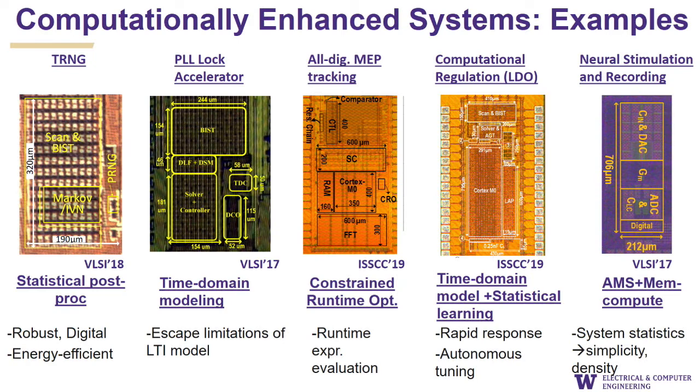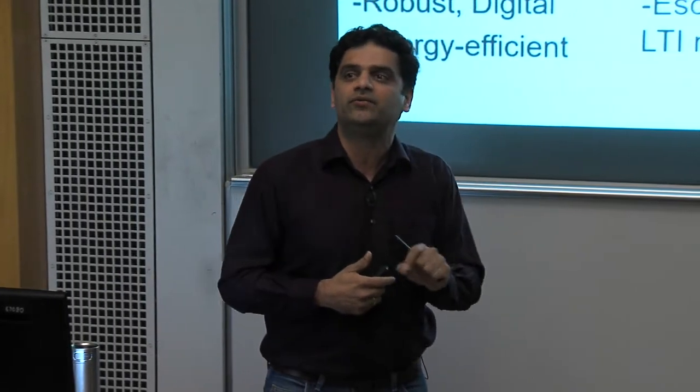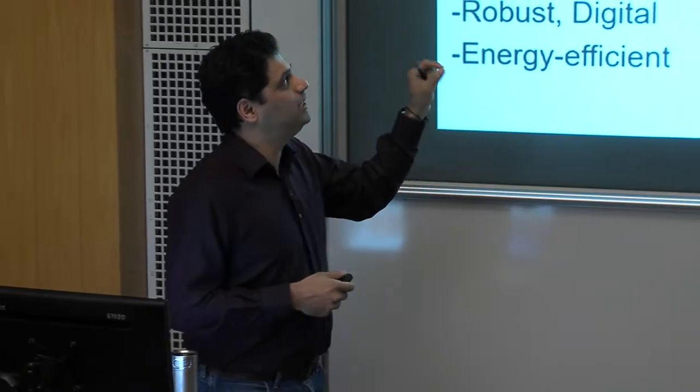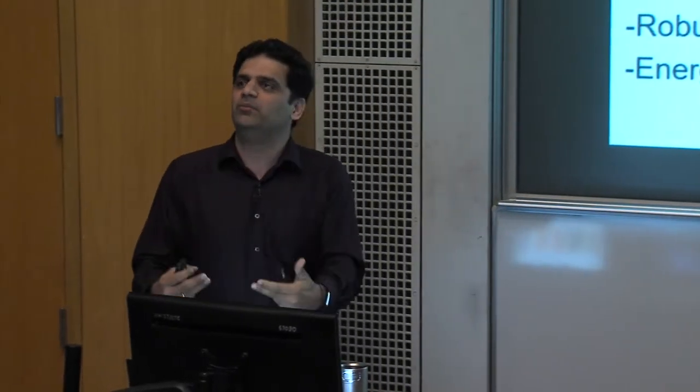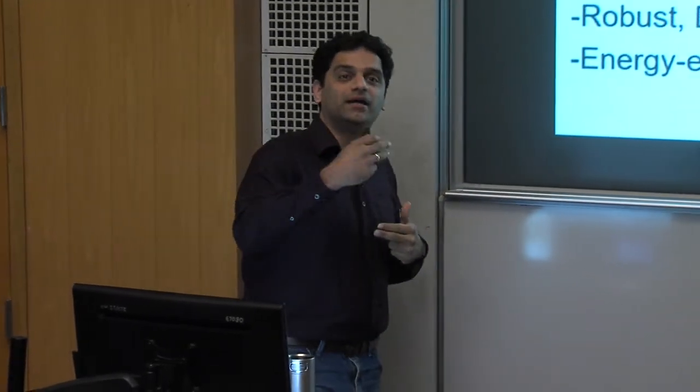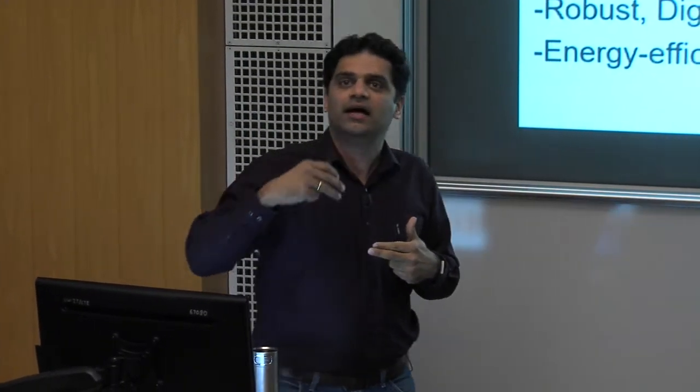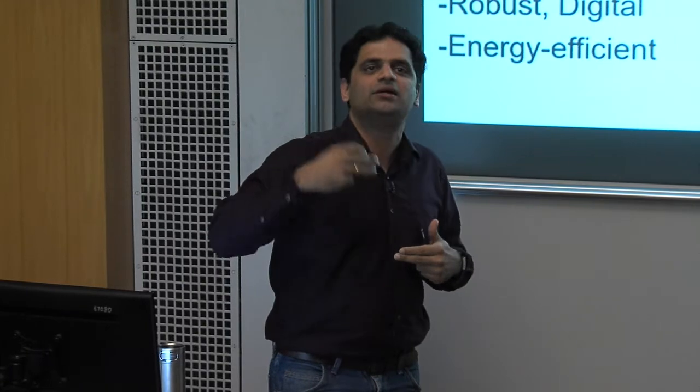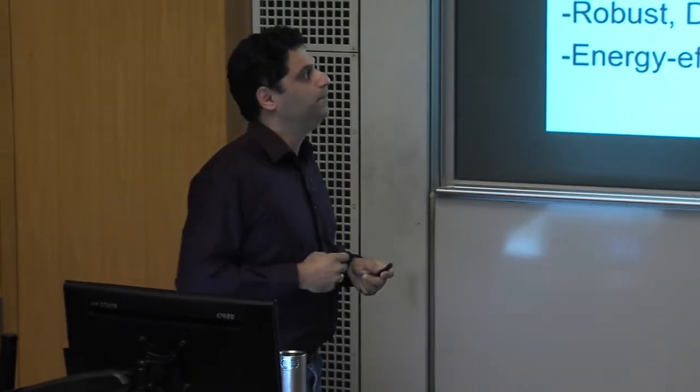And the observation there is, instead of implementing PLLs as type 2 PID systems, you instead view the problem of lock as a time domain optimization problem. The job of PLL lock is essentially solving an iterative optimization problem that achieves zero phase error in minimum time. And each reference clock cycle, for those of you familiar with PLLs, is basically an iteration in this iterative optimization problem, right?